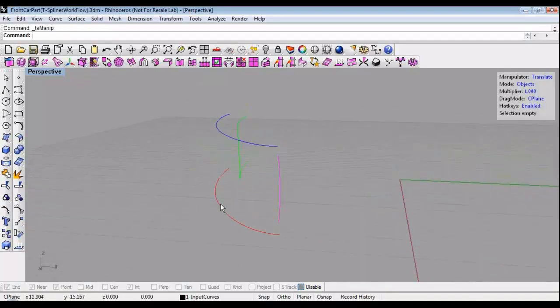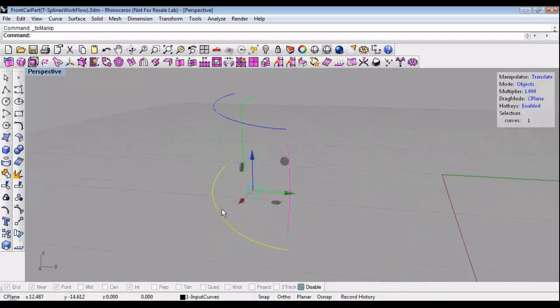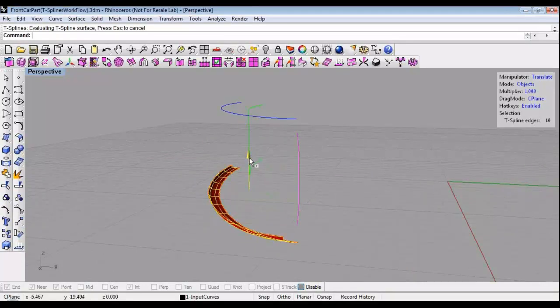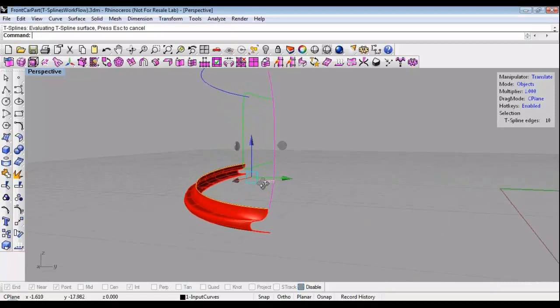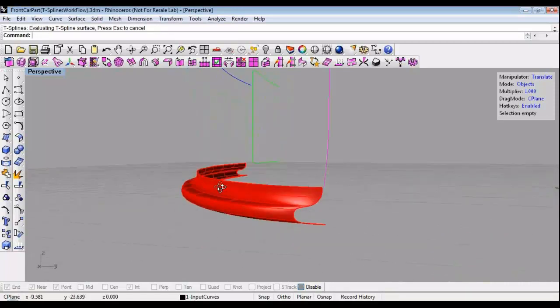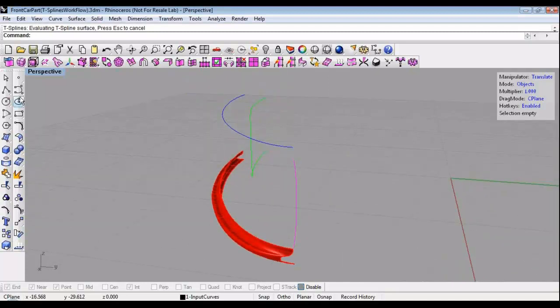with the T-Spline's manipulator. So I can just select this curve, make sure that the manipulator's on, and then if I hold down the Alt key and drag the manipulator, you can see that it's actually growing the surface as I'm dragging the different parts of the manipulator. So I can even drag these discs and it will pull it in this plane, and then drag the manipulator to bring it up. It's almost like a dynamic loft that just lets you create the surface from these curves.